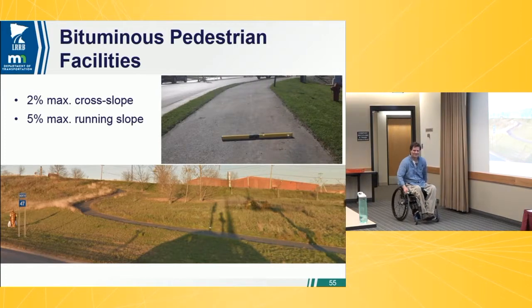Paving platform. Yep. Good. So again, that upper picture shows where it gets rounded with the pavers. Happens all the time. Again, here is where we talk about trail profiles. You know, they should not exceed 5% according to ADA standards. Our bike manual does allow it to exceed 5% for certain portions.